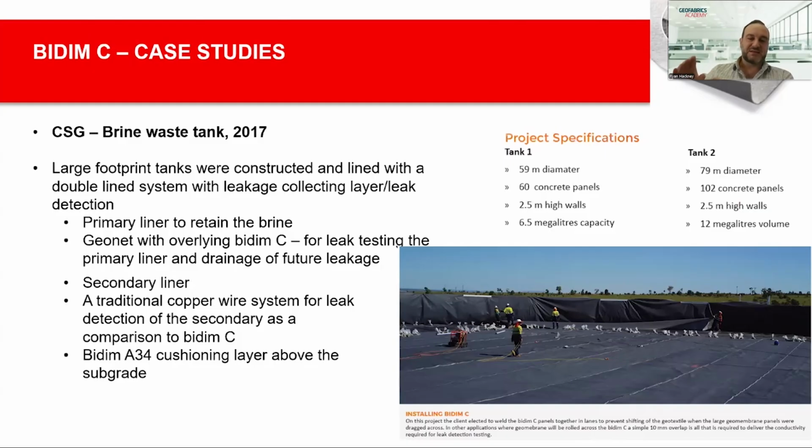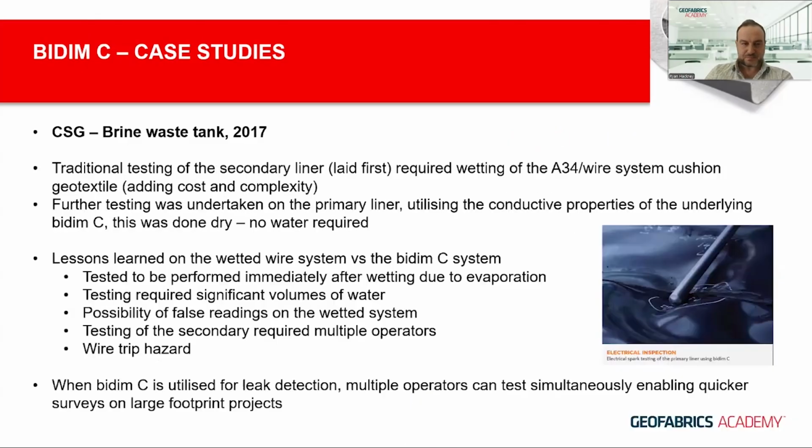And then, because this is the first time the operator used the Bidim C, they also did a sort of benchmark test with the traditional leak methodology underneath the secondary liner. So this included a copper wire system with the geotextile sufficiently wetted to enable a survey.